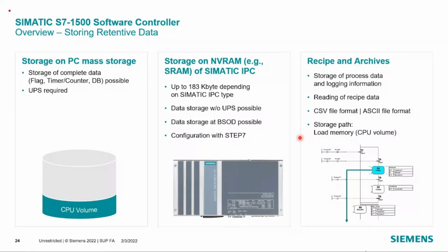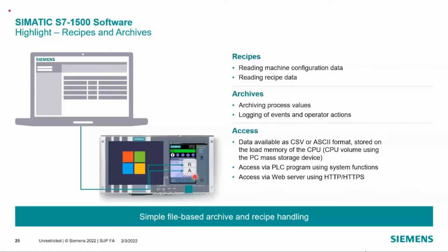From the retrieving point of view, again, it is providing the functionality over the web server. If somebody is working on recipe management on the SOP controller, that can be retrieved and archived via this web server, and that can be accessed within that PC itself. You don't require any external PC to reach this web server. The web server can be accessed within this PC system, so that is very well possible.